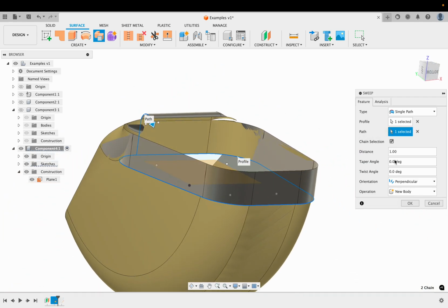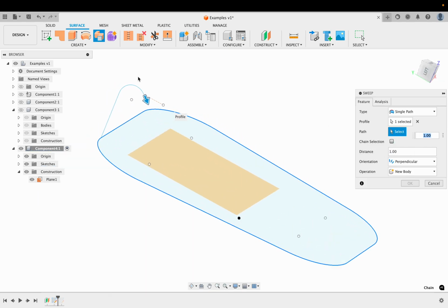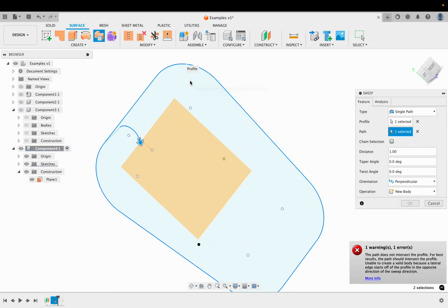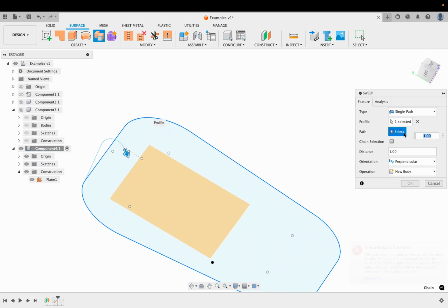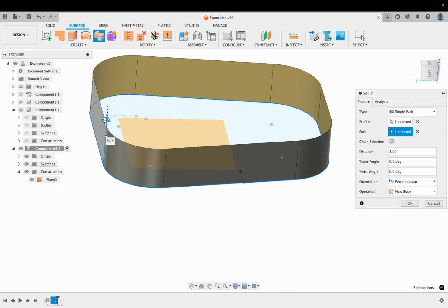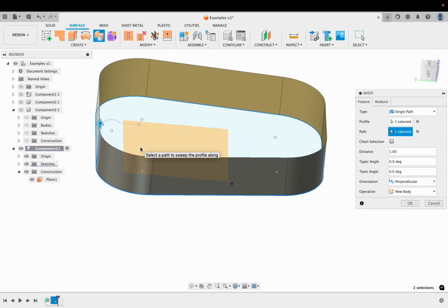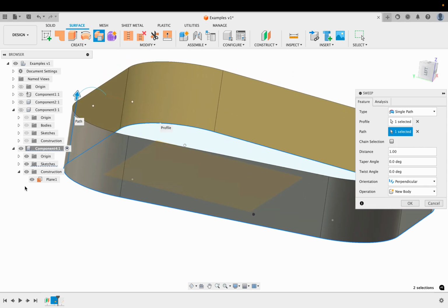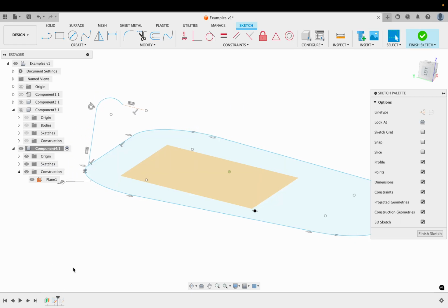That's a complete mess. Let's see. Don't chain. It's self-intersecting, which is a pain. Let's see if I can do it just with this. I can do it just with that. So what's happening here is that this radius is probably too sharp, so it collides on itself. That's what's giving me problems here. So I need to solve that in some other manner. I think maybe I'll try and solve that first. So let's try and make that a bit smaller.